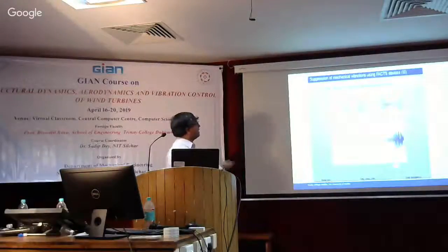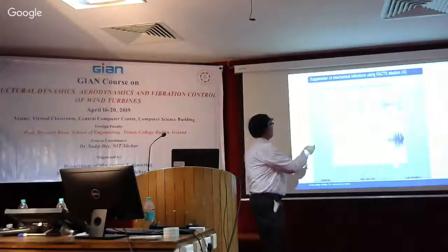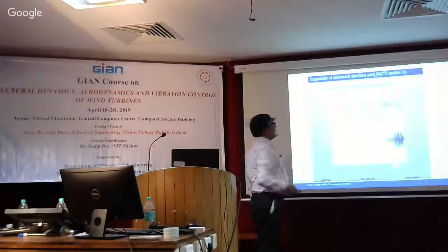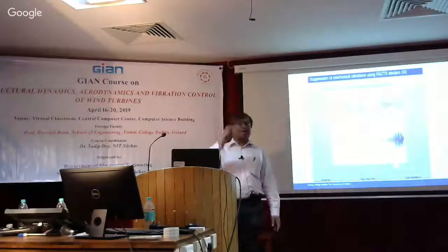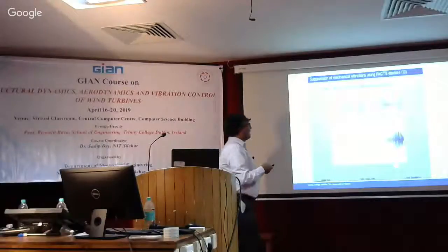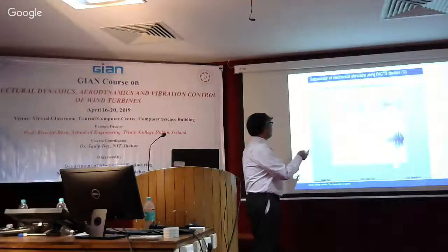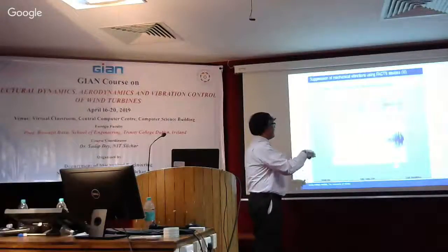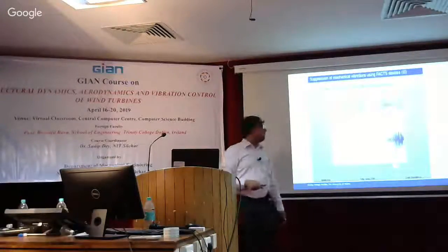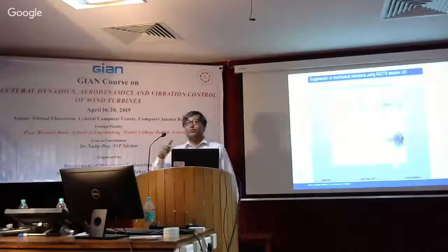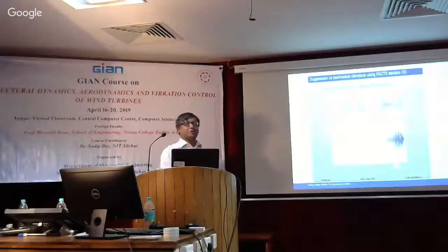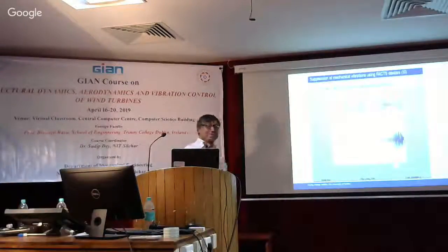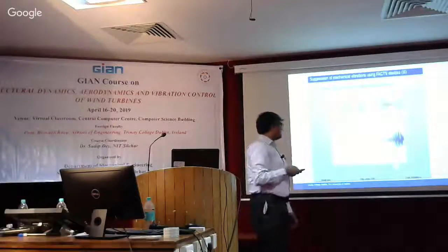So you can see this is the location where the fault happens. The fault happens for a few milliseconds, maybe 100 milliseconds. That's the time scale. But then that induces large vibration in the blade and nacelle. The nacelle response is spectacular. You can see it actually has a non-zero mean part and then vibrates violently. And this is what was actually observed by people in 2002-3. They were concerned about the vibration, and they didn't know exactly why it was happening, but this is the reason.